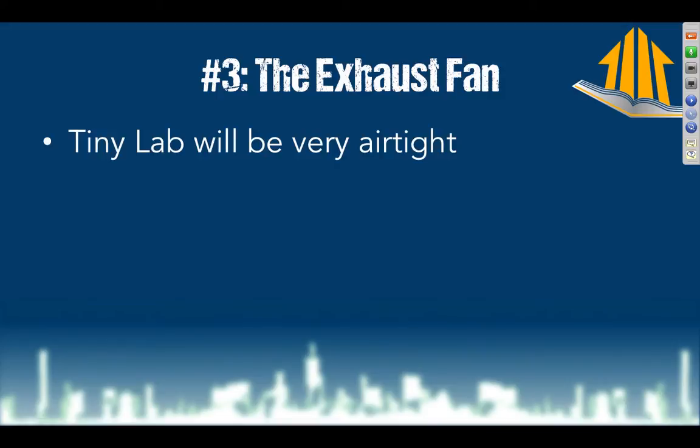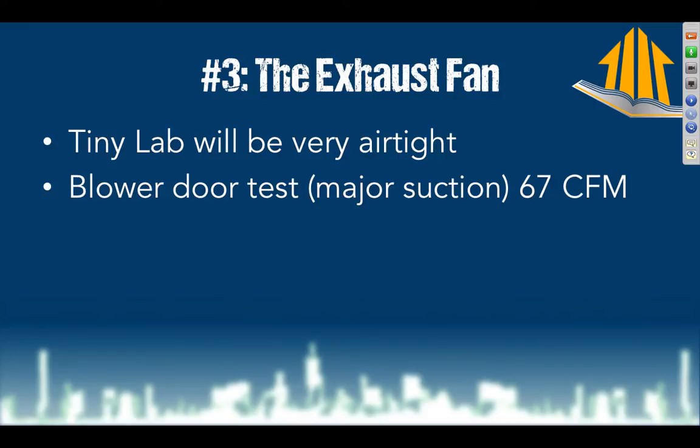So here's the main way we're going to prevent liquid water from becoming a problem, aside from the rain issue. Number one, remember that our tiny lab is going to be 2 air changes per hour or less. That is 67 CFM. If you come visit us on the tour, we will be doing blower door tests and all kinds of different tests on this tiny house to show how this all works. Do a blower door test to 50 pascals on my tiny lab, and you would hit 67 CFM. That means I'm going to have to basically take no leaks out of my blower door, if you know how this works.